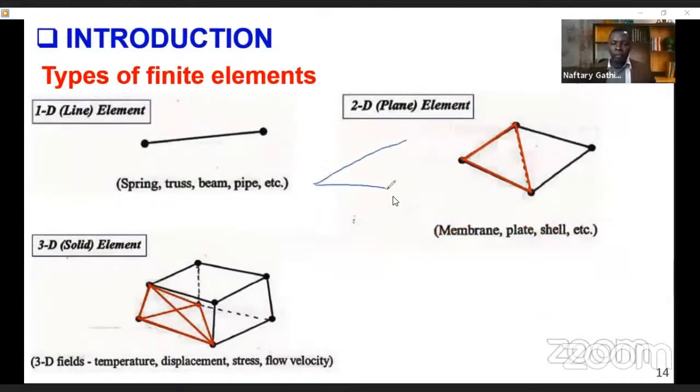But if we consider that slab, the thickness is so small here. So we talk of thin plates, such that when you discretize, we can disregard this. Or the case of plane strain or plane stress consideration, where the stress has that direction, we have that direction, and we have the depth direction. But if any of the principal stresses and the shear stresses perpendicular to this plane are equal to 0, we end up having what you call plane stress or plane strain, depending on whether you are considering stress or strain.